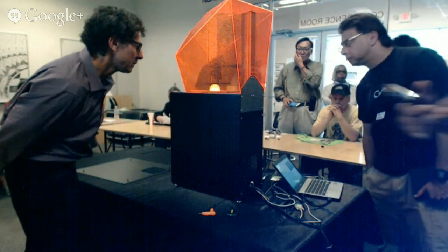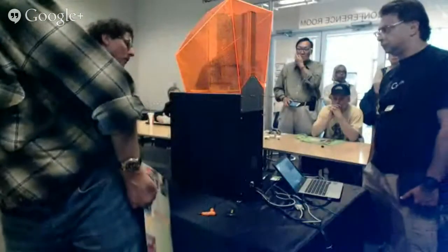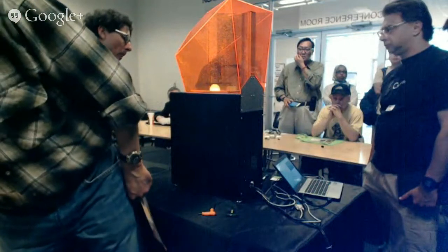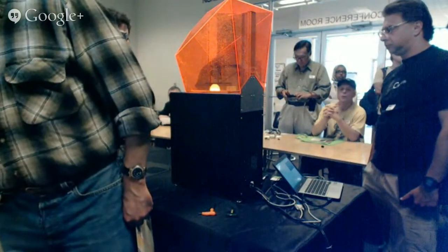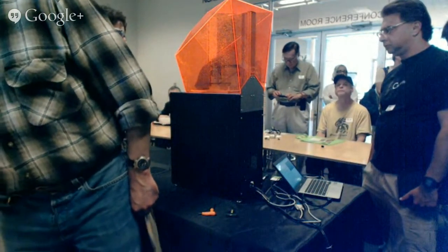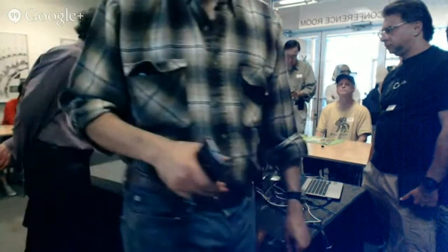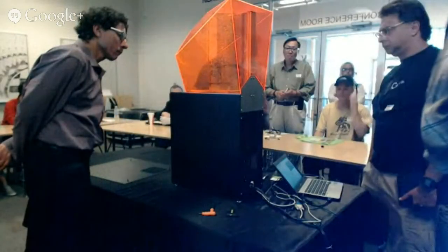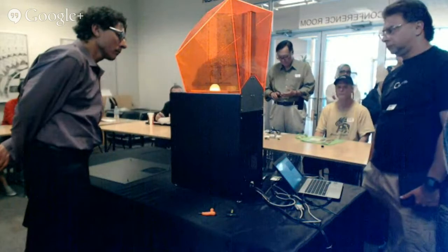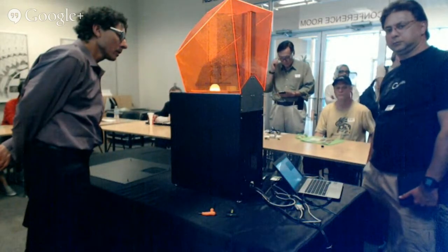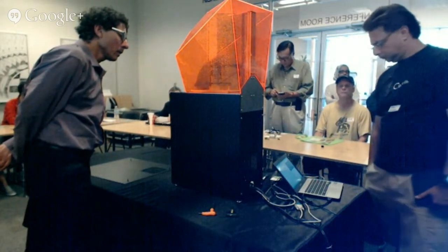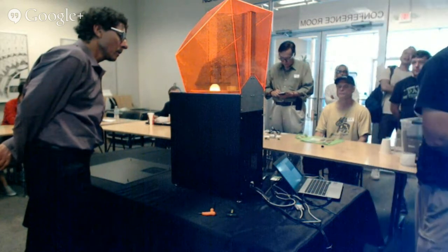But it does mean that the part does not release all at once, right? It releases gradually, and if you had a really big part that's long like this, I would only need to lift like 1 millimeter to get one end, and then I'd probably have to get to 7 millimeters before this end here finally comes off. So you need to be lifting enough to release, depending on how strong the part is sticking.